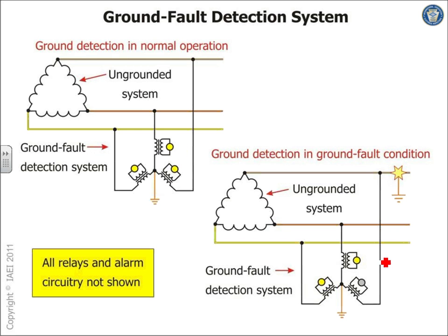If you have a ground fault in phase A, say this was phase A, can you see that this light went down or dead? And in a case like this one, you don't have to trip. It can give you an indication to go shut down the plant one day, around Thanksgiving holiday, when you're not making anything and everybody wants to go home, shut down and check for your ground fault.